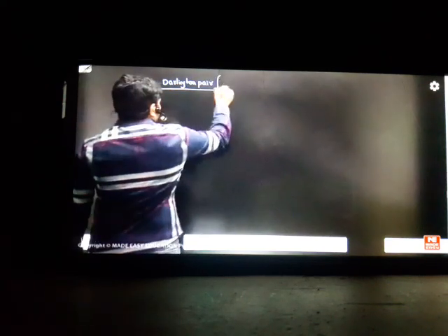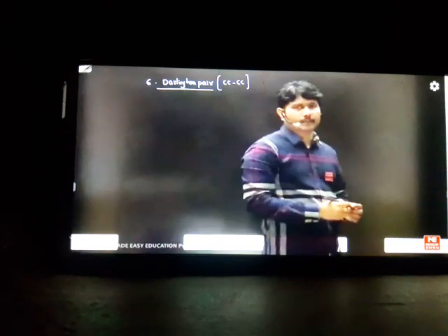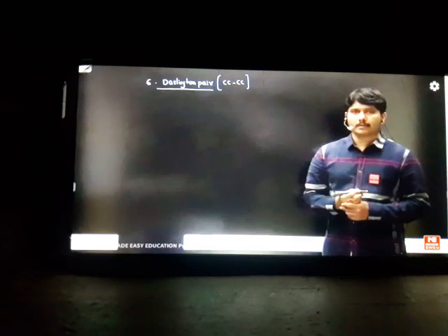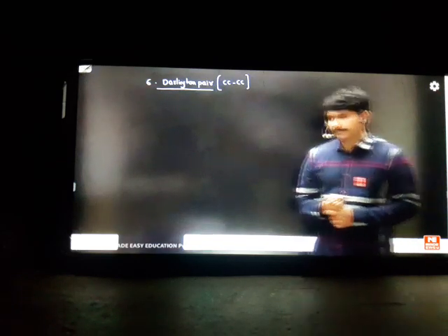Darlington pair, which is called common collector to common collector. One thing you remember, Darlington pairs we are not designing with MOSFETs. We are designing with BJTs only, because the main purpose is to increase the input impedance. Already in MOSFET we have high impedance. Darlington pairs we don't want to design for that, especially for BJT classes. Darlington pairs we call.